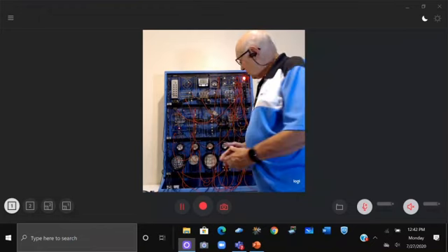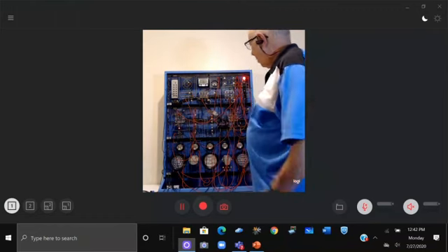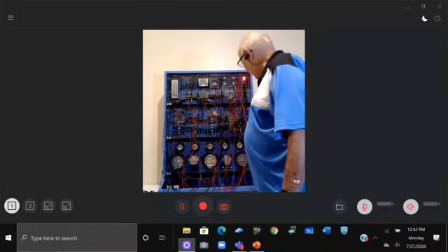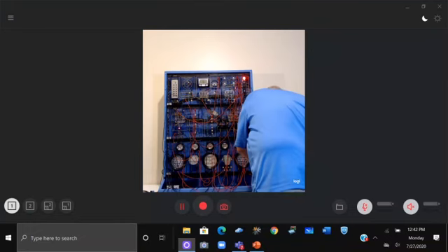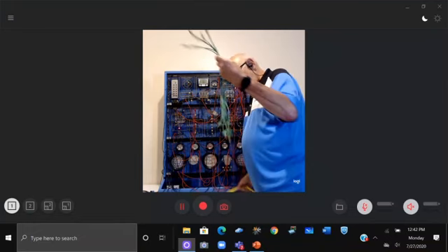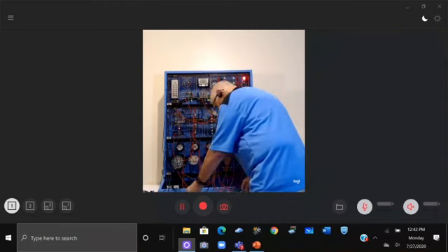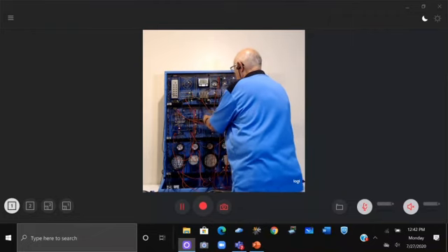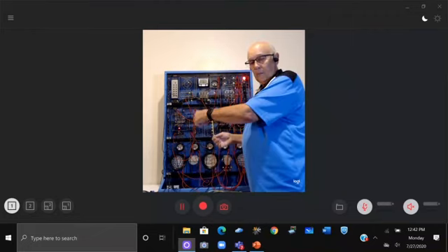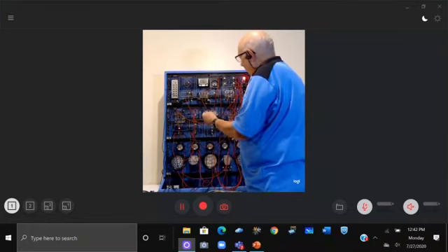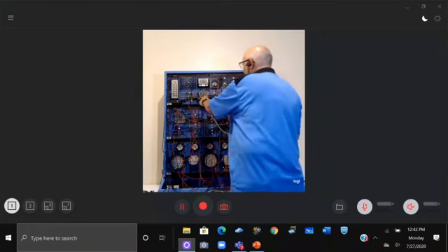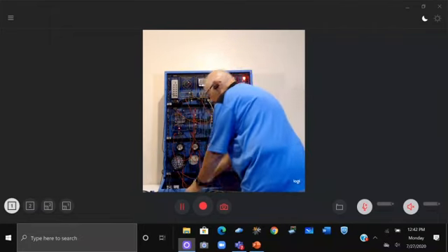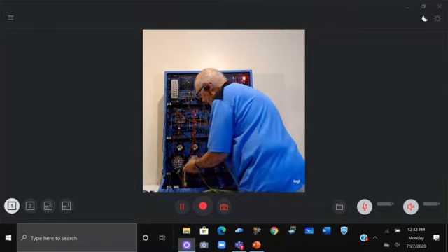Okay? So now, why don't we have any communication here? Well, why don't we have any light here? Well, we don't have light because we have no communication. So I'm going to turn that back off. Green, yellow. If we start, now again, I realize that it's a little hard to see, but I'm just in the junction block. So then we have 4 modules. So I'm going to go up to the first module, which is the instrument cluster, and I'm going to connect a green and a red, green and yellow, excuse me.